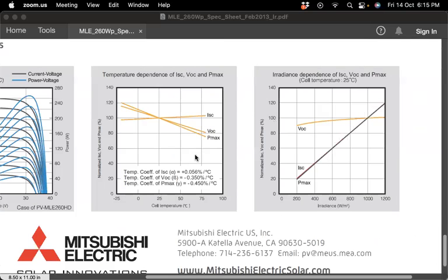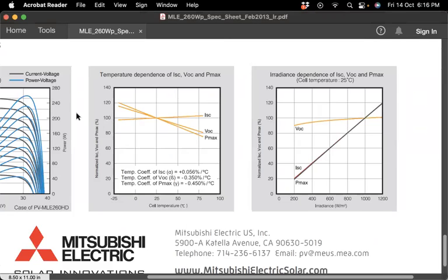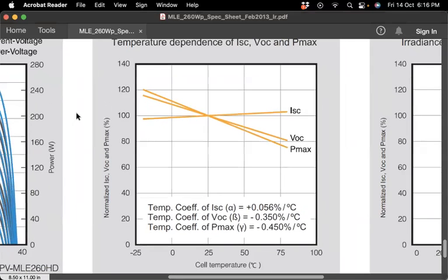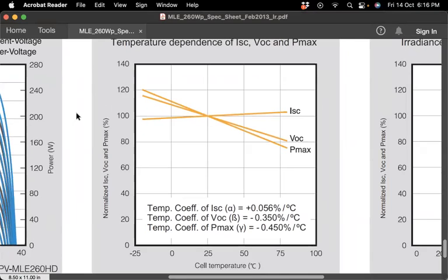Herein, the temperature effect. This is a very, very important graph related to each solar cell, describing three very important parameters, what's called alpha, beta, and gamma. The alpha, beta, and gamma are the three parameters describing the variation of the solar cell parameters with temperature. As I mentioned with solar cell radius, we can study this phenomenon mathematically, referring back to the IV characteristics equation. However, to make life easy for you, we are just going to demonstrate this in a conceptual way.